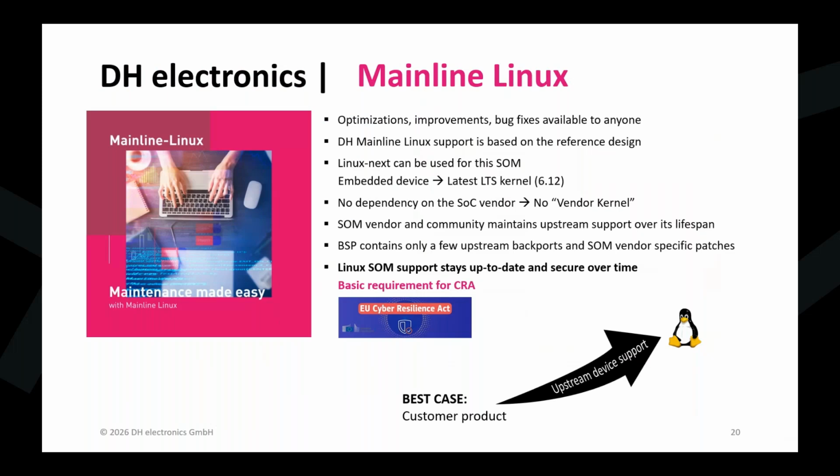The next slides will cover mainline Linux, update concept, maintenance, support, SBOM, and the CVE check. So let's start with mainline Linux and our board support package. The most important point is that we are not using the vendor board support package from ST, NXP, and the reason is simple. We like to be vendor independent.